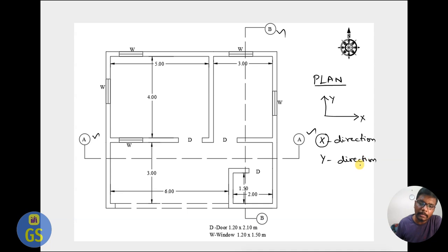We can also say it in terms of navigation, so it's better to say in the navigation aspects: north facing, east facing, south facing or west facing. So which side you are going to take a section. If we take a section like this, east facing, we put a word called east facing wall. So we are seeing the west facing walls. If you are cutting a section over here, we are cutting a section for the south facing wall, we are seeing it. These are the things you need to understand when you cut a section and when you see the objects.